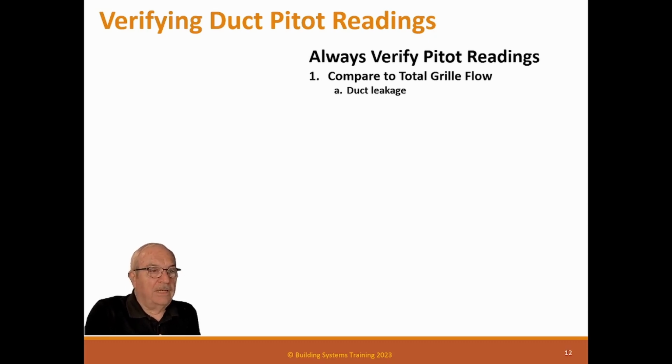If your pitot is less than the grills downstream, I suspect you have an accuracy problem. Instrument calibration could be a problem. If the flow head calibration is off, or your pitot instrument is off, you could have a difference.